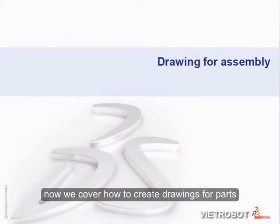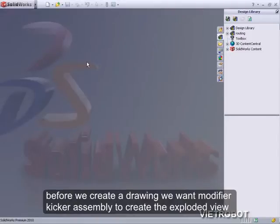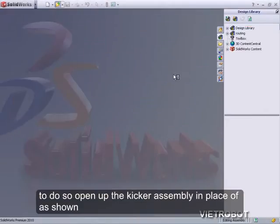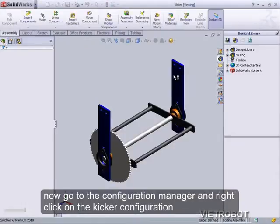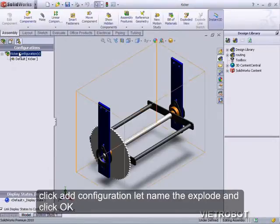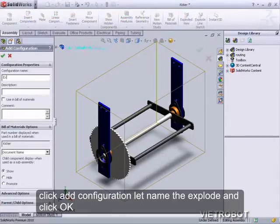Now that we've covered how to create drawings for parts, we'll learn how to make the drawing of an entire assembly. Before we create our drawing, we want to modify our kicker assembly to create the exploded view. To do so, open up the kicker assembly and place it as shown. Now go to the Configuration Manager and right-click on the kicker configuration. Click Add Configuration, let's name it Explode, and click OK.